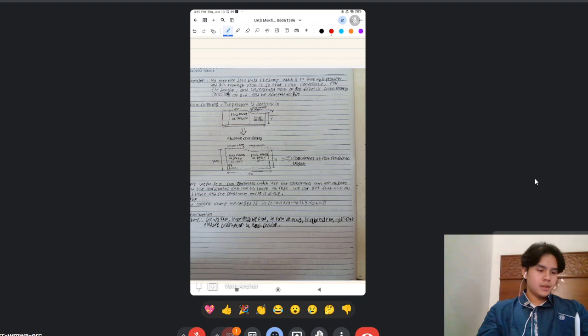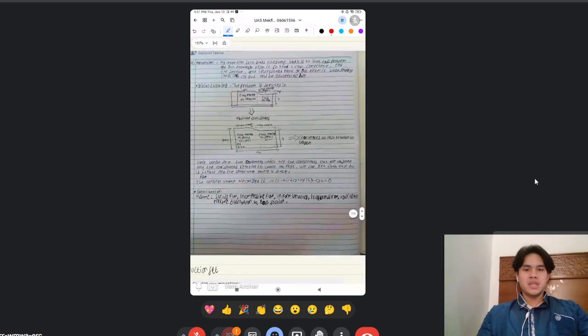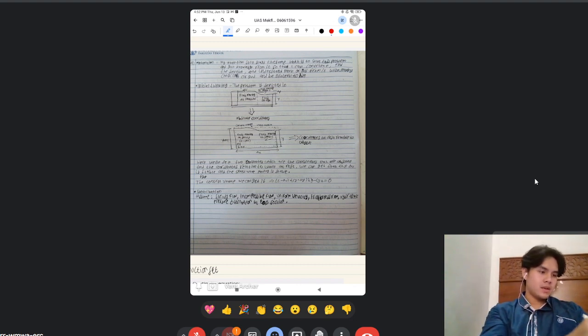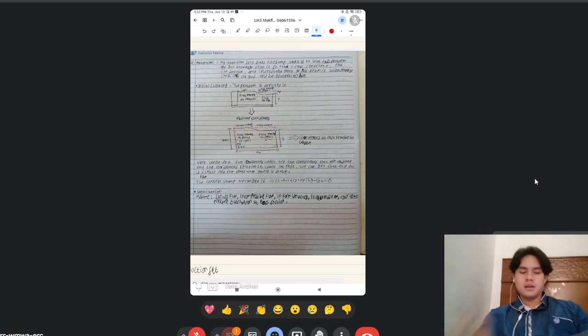And we can change this depiction and put it at another, relative to the absolute coordinates, and we'll get that fluid is moving at speed c minus delta v, so speed c is constant, and this here is the wave at rest, and then this is the control volume, the fluid moving at speed c. It's almost the opposite, but it's just another perspective from an absolute coordinate.